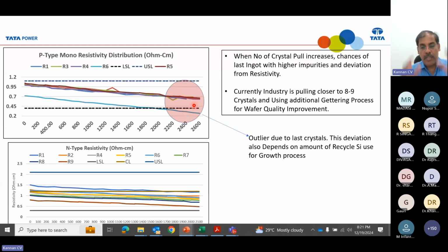Whatever crystal you grow, you have to convert into the next process instead of slicing and recycling it. Of course, you can recycle most of the parts you cut from this grown ingot, but still your overall conversion yield will go down. That will impact your manufacturing cost.